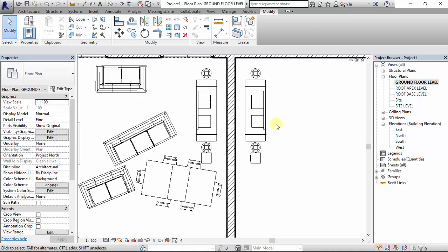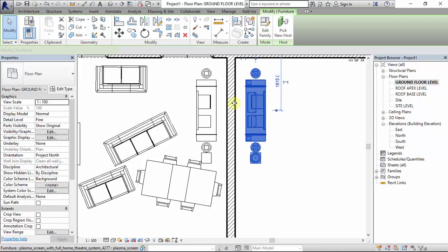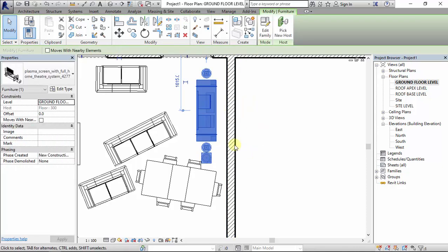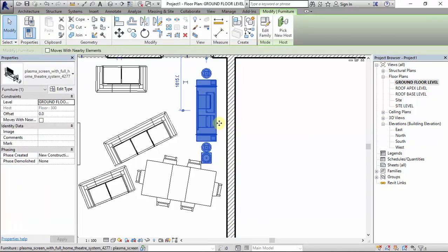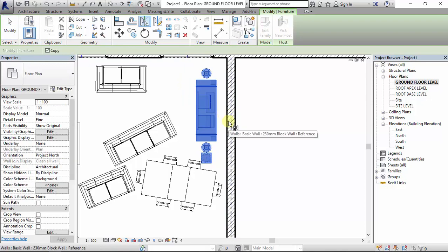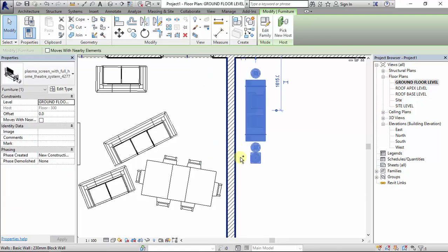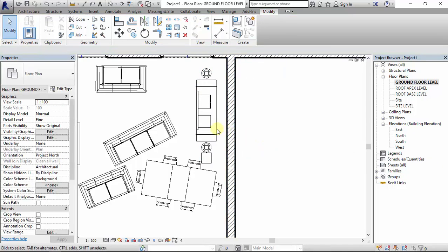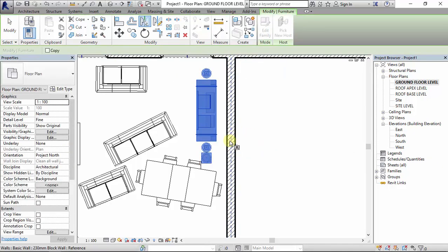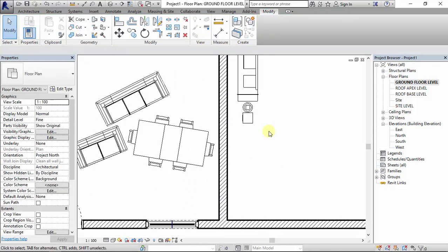But if we don't want it to copy, we just want to move it here but flip it, rather than coming here, hitting on your keyboard, then come here to deselect. Before you do that, you can easily select it, press, hold the control button, then it flips without copying. If you hit normally, it copies, but if you deselect, hit, hold control down, it does not copy.